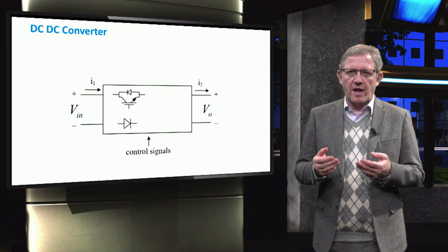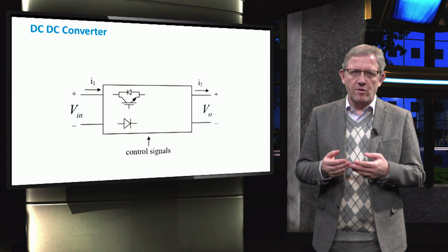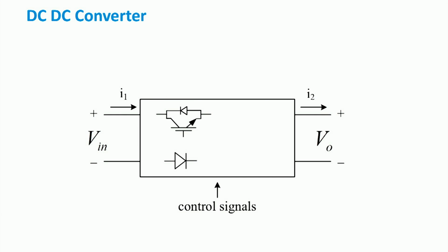Then we introduce diodes, which enter the on state typically when the switch turns off. These antiparallel diodes or freewheeling diodes allow the current flow of the inductor in the circuit of the converter. Finally, as already discussed, capacitors are used to reduce the voltage ripple at the output of the DC-DC converter.